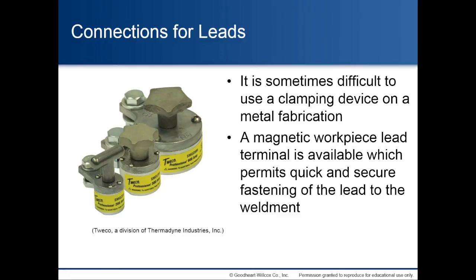Connections for leads. It is sometimes difficult to use a clamping device on a metal fabrication. A magnetic workpiece lead terminal is available, which permits quick and secure fastening of the lead to the weldment. Notice in the picture the different amperages for the different lead terminals. Also, these can only be used on magnetic material.